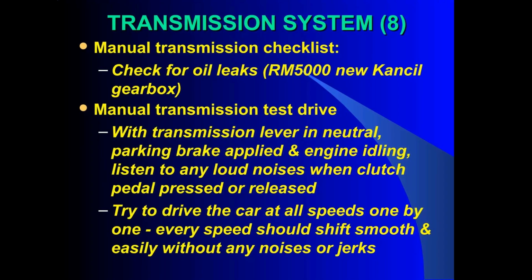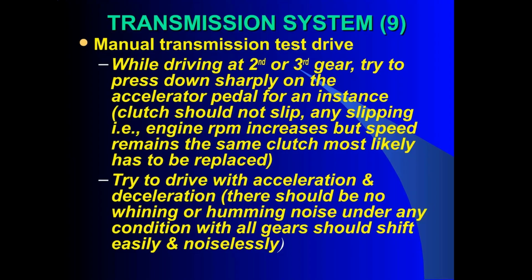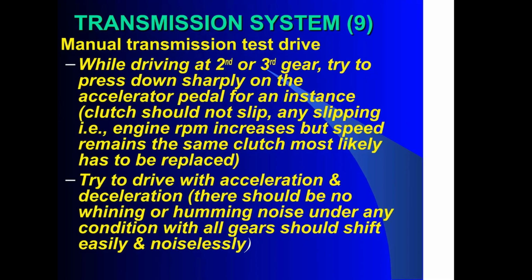When checking a manual transmission, look for oil leaks. During a test drive in neutral, listen for loud noises when pressing or releasing the clutch. All speeds should shift smoothly without noises or jerks. While driving, try pressing sharply on the accelerator in second or third gear. If the engine RPM increases but speed remains the same, the clutch is slipping and needs replacement. Listen for any whining or humming noises during acceleration and deceleration.